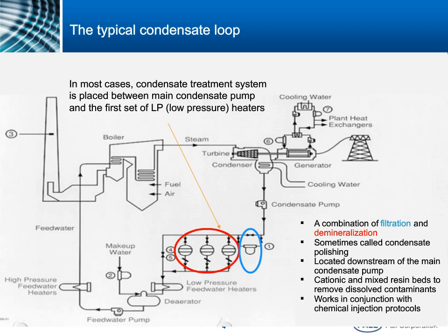Now, of course, depending on the nature of the plant and the pressure of the boiler and overall the operation and cyclic conditions of the plant, you may find one or the other. In some cases, this is empty space and you have nothing. So basically water is redirected without much treatment all the way to the boiler. Obviously, as plants become more critical and larger, when the pressure goes up, it's extremely rare to not do anything for the feed water. But we'll see how the two can combine, this filtration and demineralization, and how the two can play upon each other's strengths to really get to the results we're looking for.